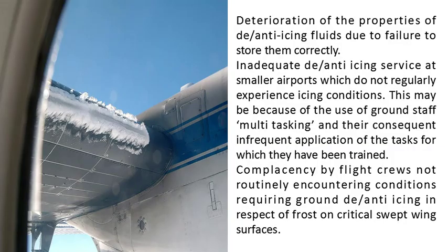Deterioration of the properties of the anti-icing fluids due to failure to store them correctly. Inadequate anti-icing service at smaller airports which do not regularly experience icing conditions. This may be because of the use of ground staff multitasking and their consequent infrequent application of the tasks for which they have been trained. Complacency by flight crews not routinely encountering conditions requiring ground anti-icing in respect of frost on critical swept wing surfaces.